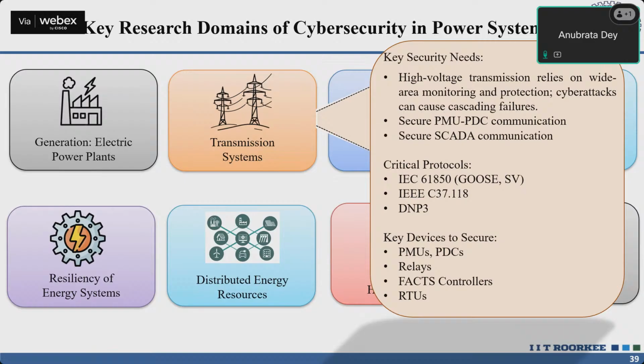The protocols they are using are IEC 61850, basically the GOOSE and sampled value based protocols, IEEE C37.118, which is a protocol for communication between PMU and PDC, and DNP3, which is used by the SCADA system. The key devices are PMU, PDC, relays, FACTS controllers, and RTUs. These are the devices where we have to consider the cyber security aspects based on these protocols.